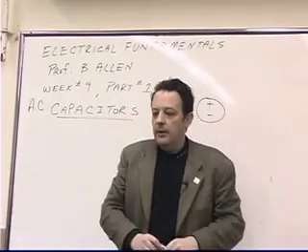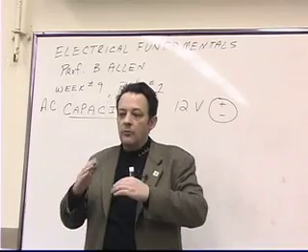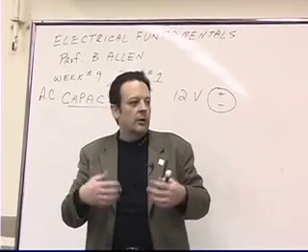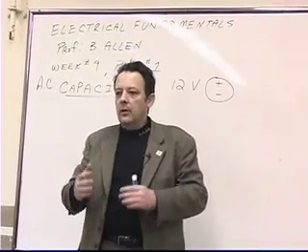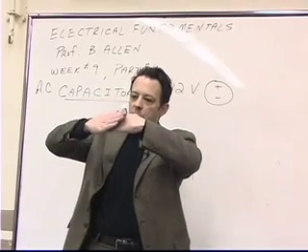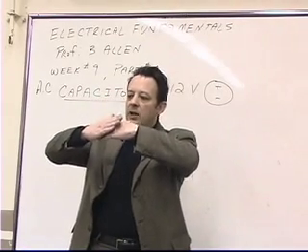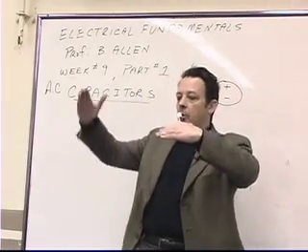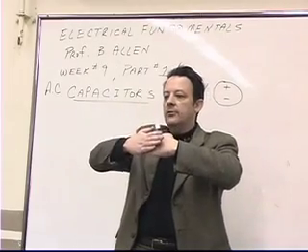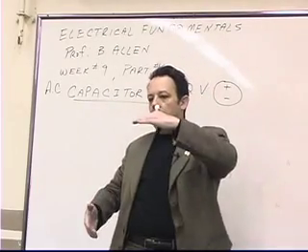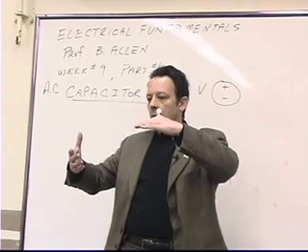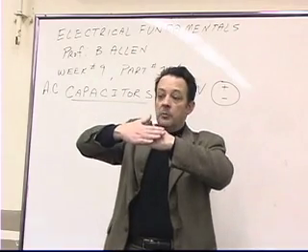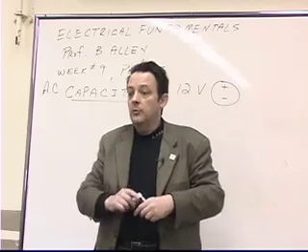In industry applications, we usually don't use air, for a lot of reasons. We use things like ceramic or rubber or other things that allow us to push the plates against each other, but have something wedged in between that keeps them from shorting out. Because if I just had a plate and I put another plate on top of it, they would short out against each other. But if I had a plate and I put some oil wax paper over the plate, and then I put another plate on top of that, there wouldn't be a short because there would be an insulator between the two plates.